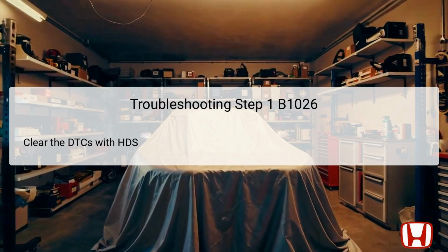The first troubleshooting step for DTC B1026 is to clear the diagnostic trouble codes, DTCs, using the Honda Diagnostics System, HDS. HDS is an essential tool that helps identify and clear fault codes stored in the vehicle's computer. This step is crucial because it will allow technicians to reset the system before conducting further diagnostics and to verify if the error persists.